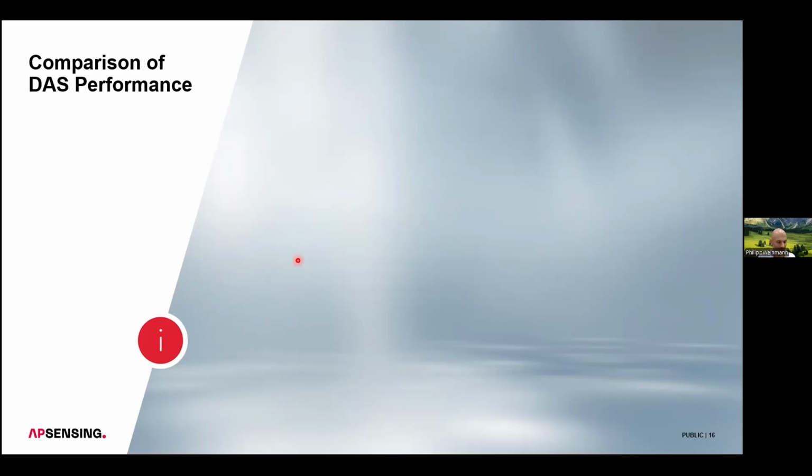Then you see where the signal is occurring in your waterfall diagram. That gives you the fiber position. Then you assign this fiber position to the GPS coordinates where you are standing right now. Good, I was going to compliment you there. Yes, by tap test. Good.